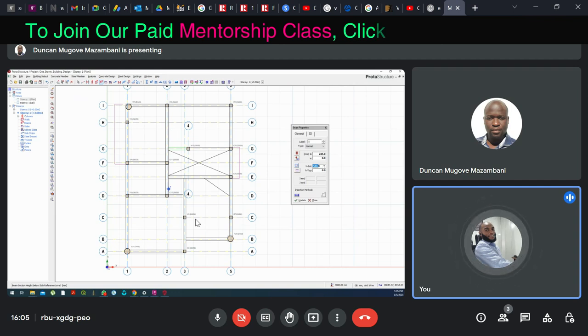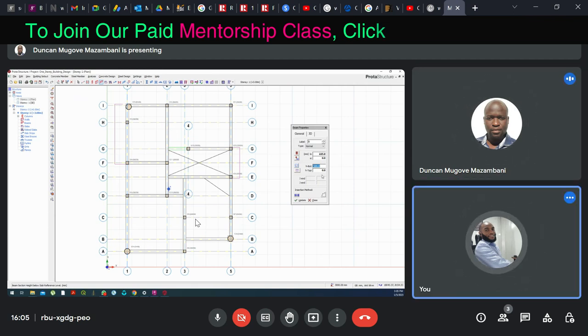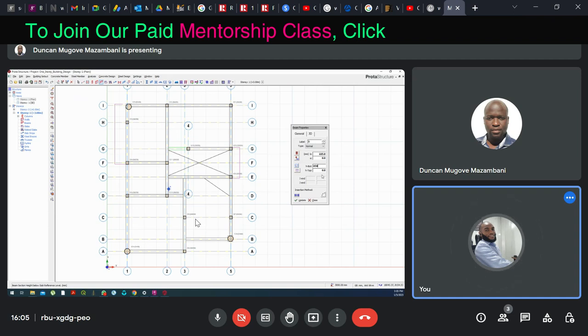Then if there's any failure, if the depth of beam is not okay, we can go and increase it after design. So type 450 there. Yes, 450, and then begin to insert right now. Click on one of the columns and click on the next column to begin to insert your beams. As you can see the shape there, that's how the beam will run. So begin to draw based on the beam. Click there and click on the next column. It will insert the beam for you.